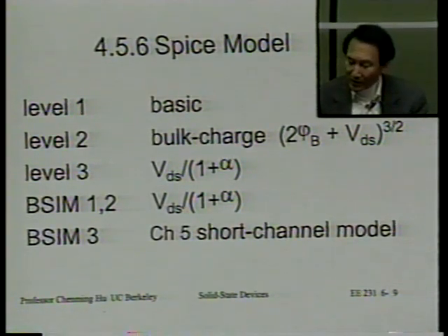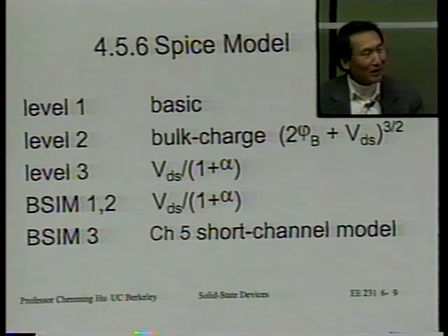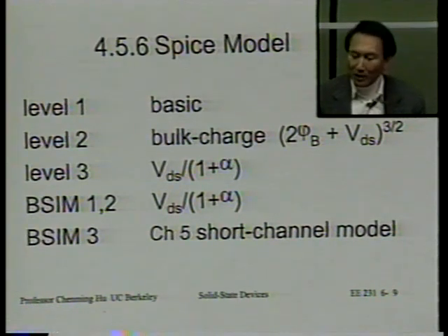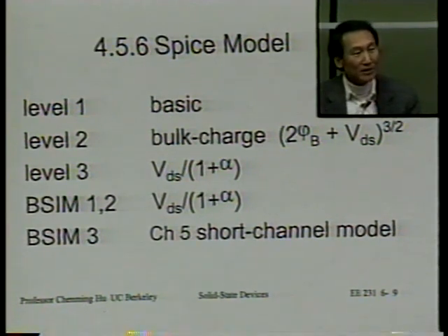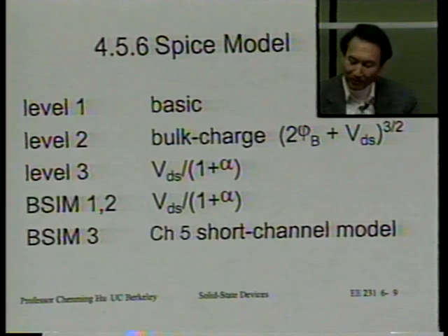It's an industry standard model, and that actually incorporates a lot of the physics that we'll be talking about in this course, not just having to do with IV, also having to do with short channel effect and maybe some other things that you don't anticipate. So after we have talked about those, I'll then give one lecture on the BSIM model to see how all these things can be used in the SPICE simulation model, in addition to be used as guidance for designing better transistors or understanding how transistors work or why these sometimes don't work.